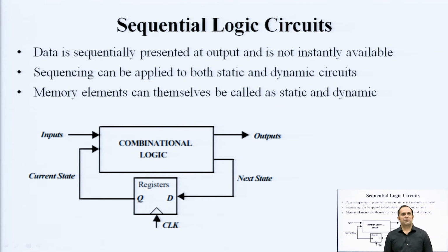So, let us see how a sequential circuit looks or works. You always need a combinational block. It can be your logic gates, an adder, subtractor, counters, multiplexers; a whole lot of combinational logic circuits you can design. You can implement Boolean algebra using combinational logic. That combinational logic, if you do not have any clock or memory, is a pure combinational circuit. Use that combinational logic, take the output and store it somewhere so that it can be used at a later stage.